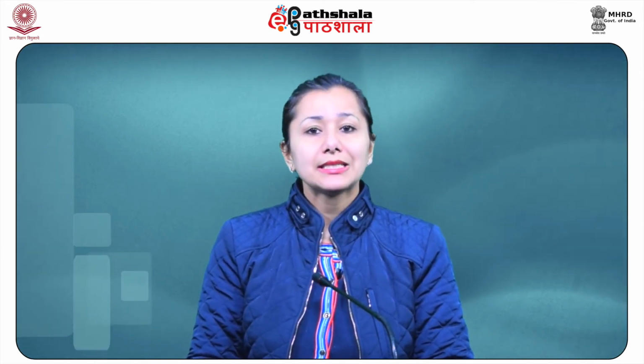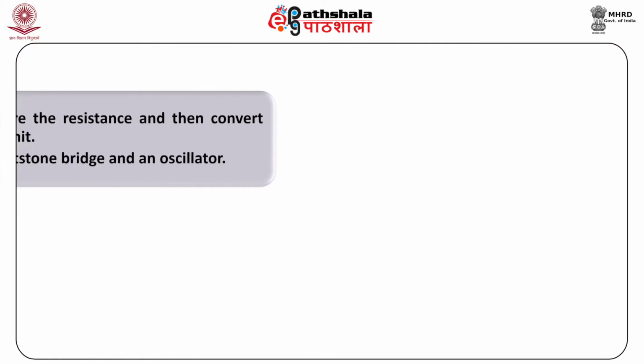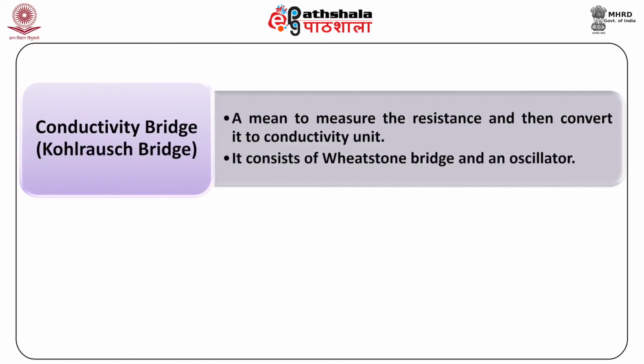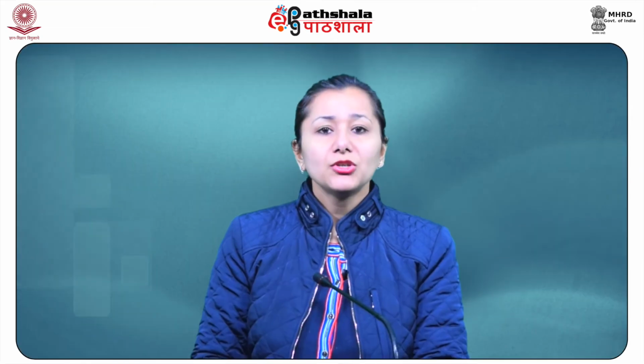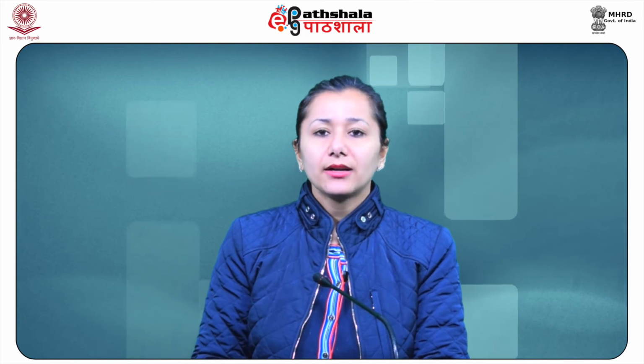The instrument consists of two parts. Number 1 is the conductivity bridge, or the Kohlrausch bridge, a means to measure the resistance and then convert it to conductivity units. It consists of a Wheatstone bridge and an oscillator. Number 2 is the conductance cell, in which the solution to be measured is filled. Commercially, various types of cells are available.